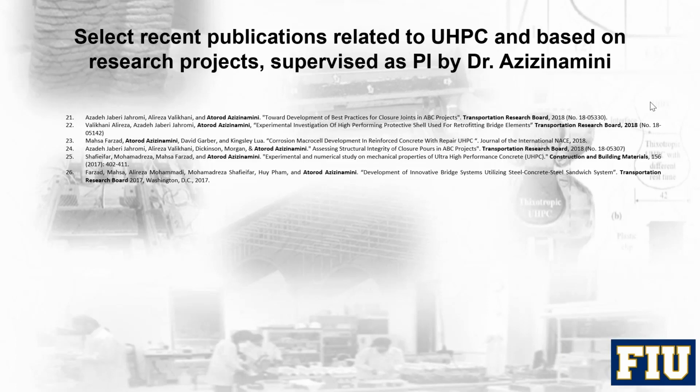Ben, could you elaborate on the very top fibers that are exposed? They get corroded, but nothing more than that. Can you elaborate on that, because there's a concern with that? Right. What we've seen is that if you have exposed fibers, these fibers are made of steel, and they'll corrode. But the corrosion doesn't progress down into the body of the UHPC.